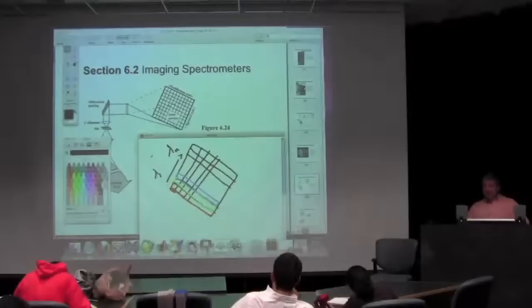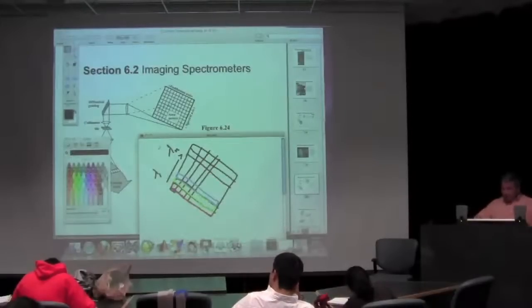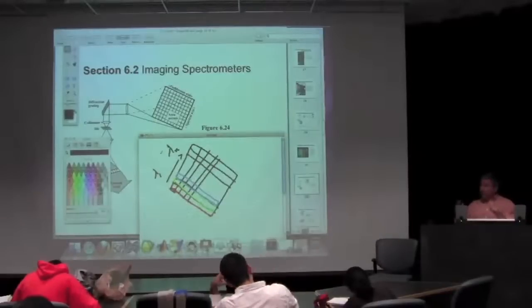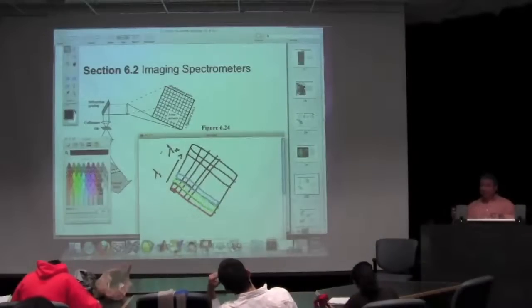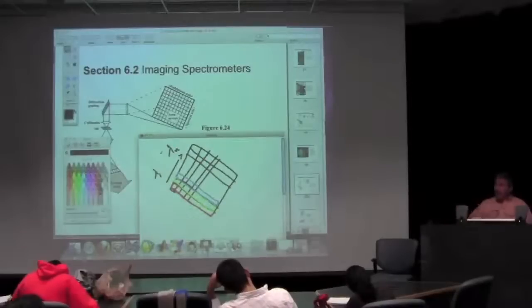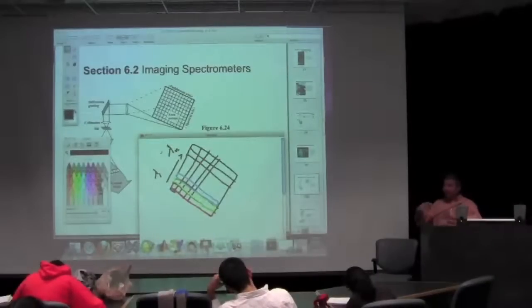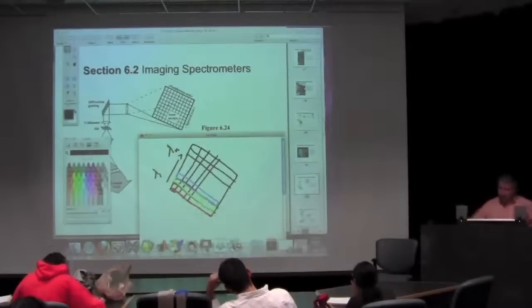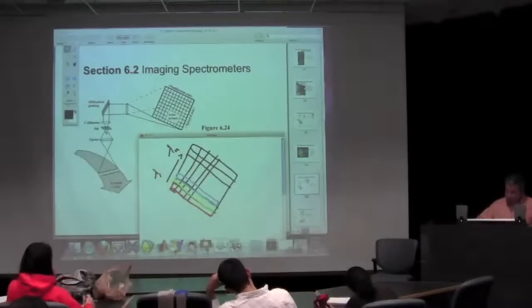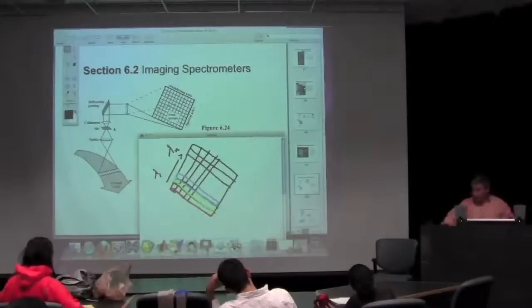Does that make sense? So you still have some geometric problems, right? If you have roll in your aircraft, you're going to get line shifting left and right. But along any single line, you're going to have very strong geometric relationships between those pixels. And now you get simultaneous spectral collection of all the bands that you want to sample for that line on the ground. Because all your imaging in this case is the single slit. You don't have any other data coming into your system. So very good registration based on color.